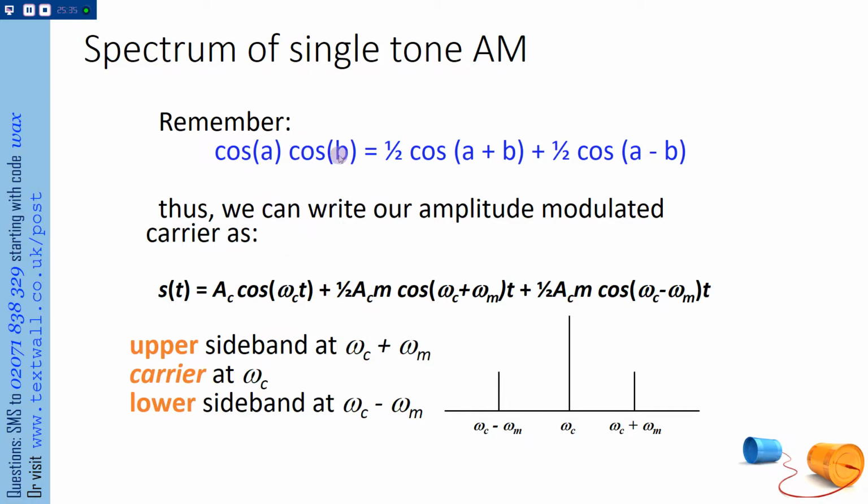So when we take our signal, let's say it was that cosine omega m. If I were to add a DC, so if this is my message, that's what the spectrum looks like, at FM, or omega m. If I add DC, that's my DC. And then I shift that, so you need to remember there's also one at minus FM.